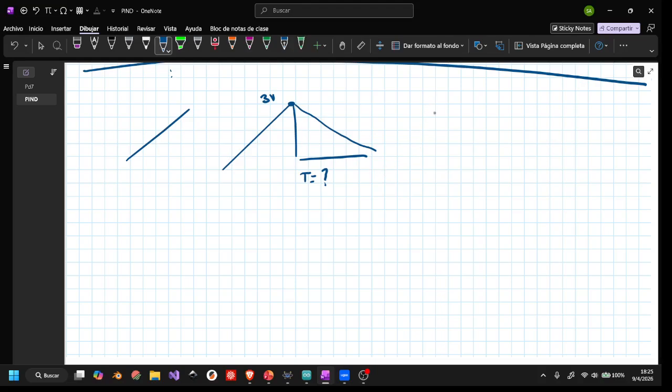So for example, if we count like this, it means that we charged very little, so the value is really small. If the counter achieves this number, it's a bigger value, right? And it's proportional, right? Because the time is proportional to the resistance and the capacitance, and both of them are fixed. So the only thing that changes is the initial voltage that we got here, right? It's called dual slope because we start charging and then we discharge, right? We stop charging when we achieve the value of the reference, and then we measure the time, right?